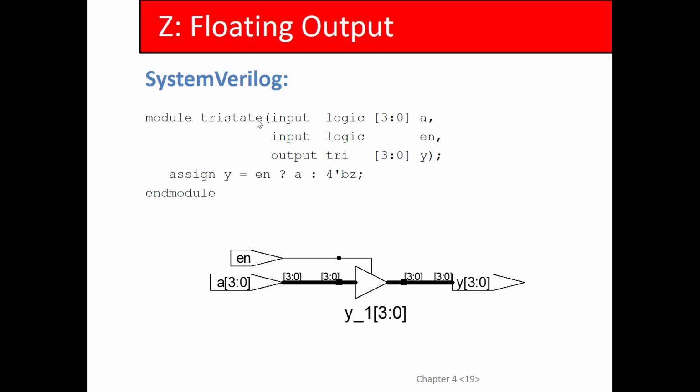See, that's the other thing. When you write code in C or Java, the slightest problem with your code will cause it not to compile. You forget to declare something, the smallest problem, and it won't compile. But Verilog is shockingly forgiving for being a very low-level language. Depending on what software you're using to simulate or synthesize, you can get away with not even declaring a variable. It'll say, oh, you didn't declare it, so I'll just assume it's declared. It is really shocking. But the problem is when you do that, it often leads to incorrect designs. So you have to be careful. You should try to be disciplined when you write your code.